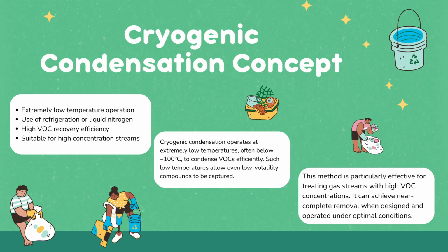Next, we jump to the cryogenic condensation concept. There are main points here. The first one is extremely low temperature operation, using refrigeration or liquid nitrogen, high VOC recovery and efficiency, and suitability for high concentration streams.